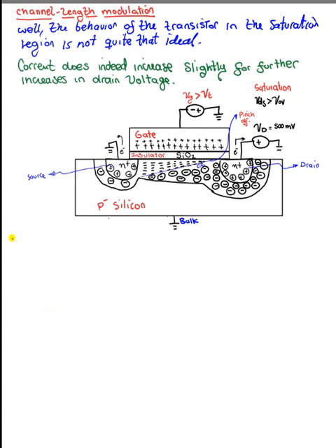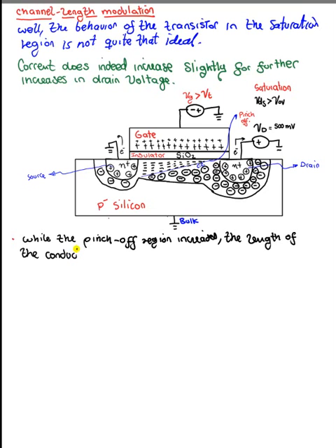So while the pinch off region increases, so this region right here increases, the length of the conductive channel decreases, right?